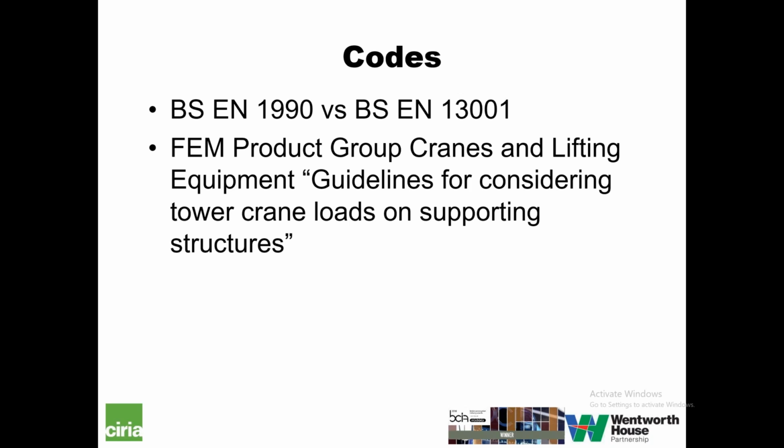So those of you like myself who are structural engineers will be familiar with the typical load factors of 1.35 on dead load and 1.5 on live load in the Eurocodes, down from the old 1.4 and 1.6. However, EN 13001 deals with a number of different situations for tower cranes, and the load factors vary from 1.1 up to 1.5.